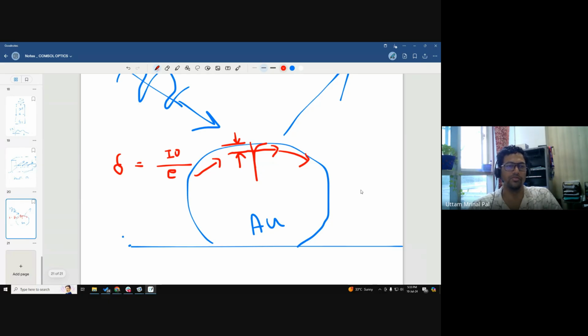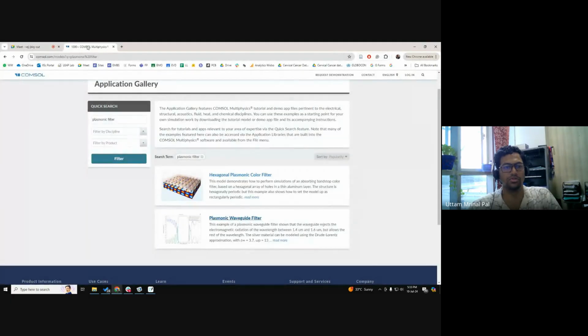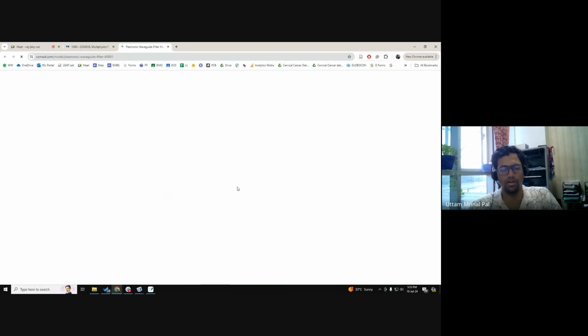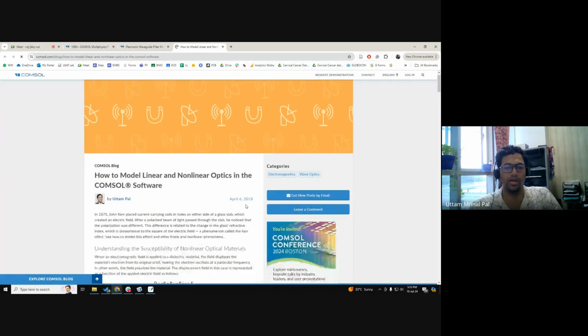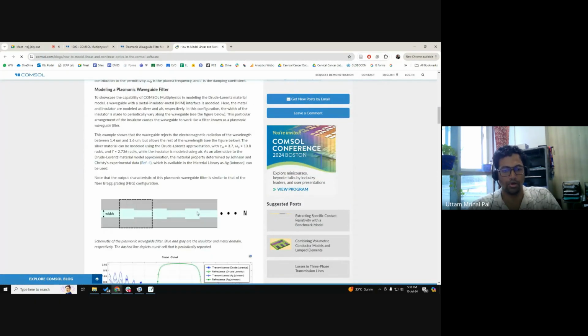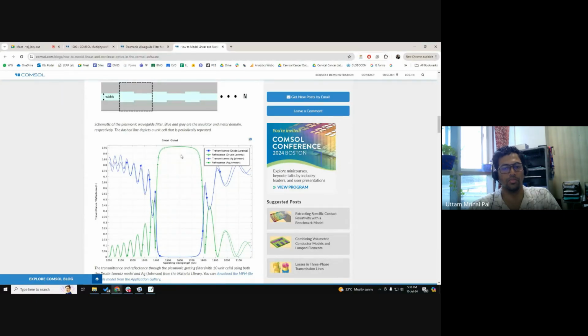Okay, because we are solving Maxwell's equations, what's the difference in that procedure? In the example model we talked about some time back, we have done it with two approaches. One is changing the material model, with a Drude-Lorentz model, and the other is applying the material itself. Both of them give the same results; you can see both of them showing the same results.